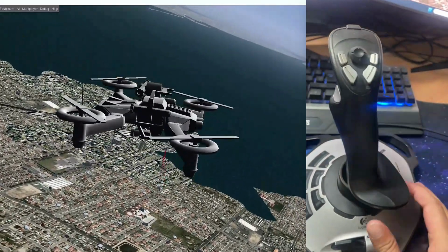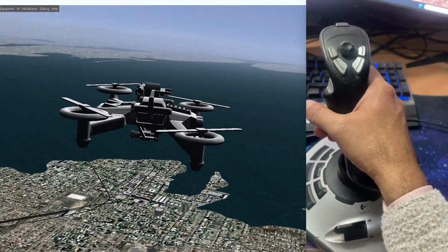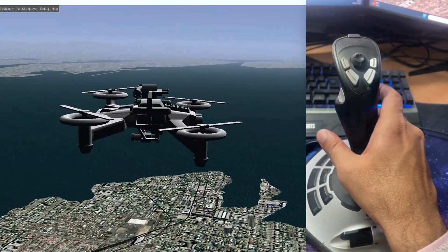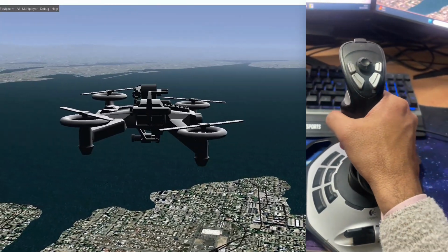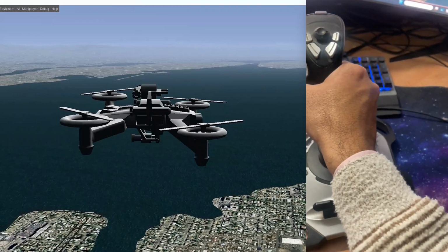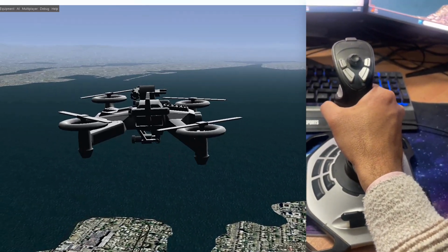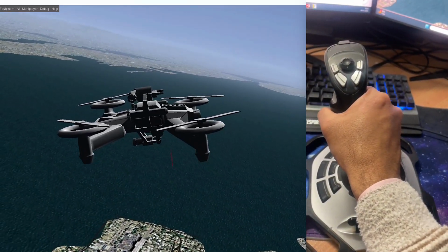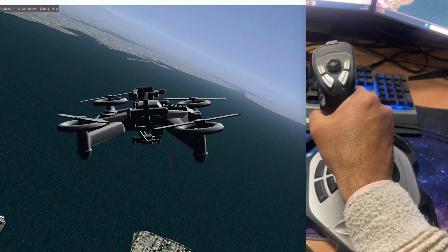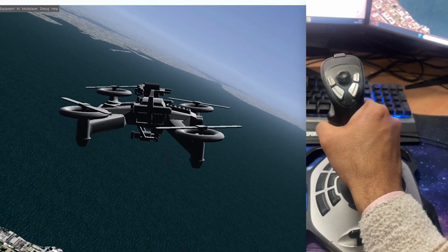During the roll, make sure you do not have some kind of twist, otherwise you will get a different kind of motion. If you want a pure roll, you have to be very careful in deflecting the stick, otherwise some yaw will happen.